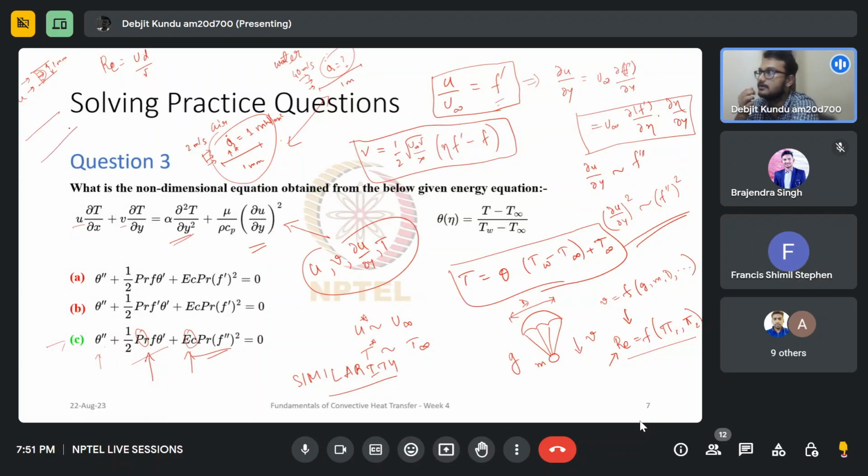Now I take a 1 meter diameter and I put some different velocity, I match this Reynolds number. So if, let's say, Reynolds number was 100 and this is also matching this Reynolds number to be 100. In that case, the velocity profile that I get here would be exactly the same as I got for the 1 millimeter pipe. There won't be any difference.